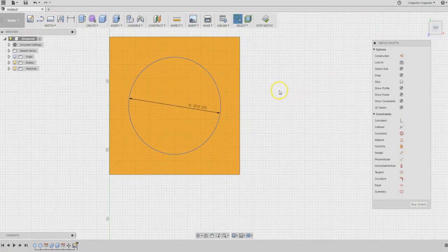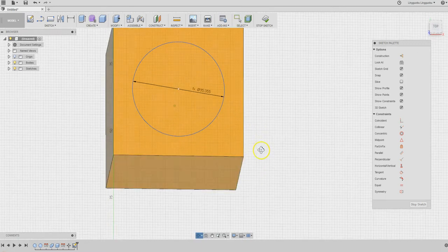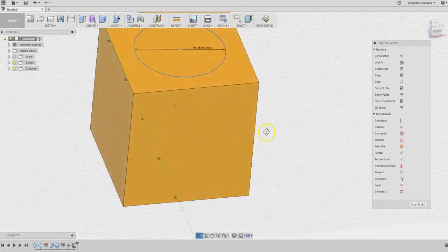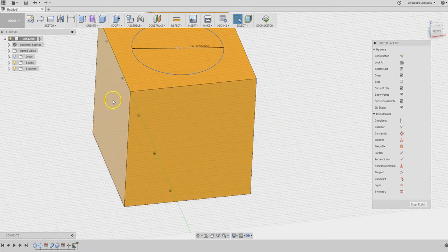Let's look at the top view here. Next, we would like to slice this circle into 2 pieces, because we only need half the circle to make the cut. If you want to, you can sketch a similar circle here or there, to perform 2 circular cuts, but because of the symmetry we are dealing with, we don't really need that.